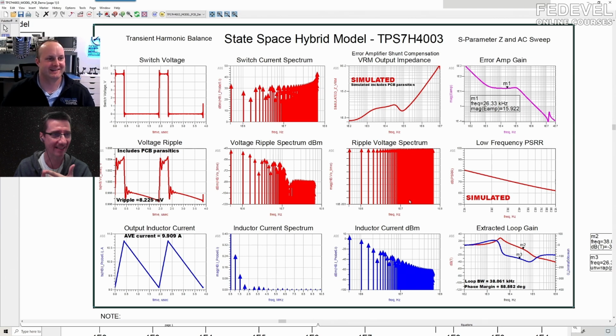The second amazing thing is how one unfitted capacitor will influence your power supply output. How is this possible? The placement matters because the placement is adding inductance, which is affecting the PDN. And this is the cool thing about tools today. You can use tools to figure out whether this is a problem, because in the real world, you need to be able to model the real world to be agile and to get the right answer. This is why I use this tool. When you want to ship something and you have a problem, whether it's EMC or ripple or whatever, how do you troubleshoot it? Well, I just showed you how, really practically.